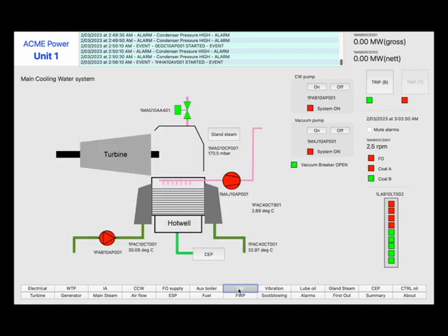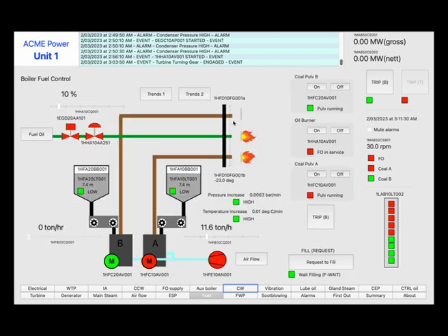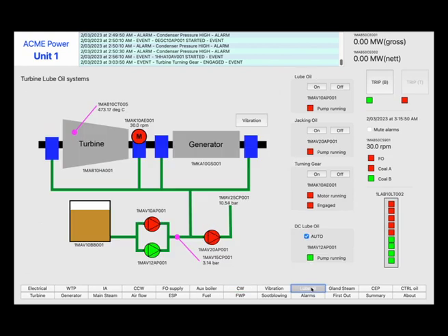Condenser pressure should reduce. Condenser cooling water outlet temperature should also reduce. As our intention is to resynchronize the generator to the grid as soon as possible, adjust furnace burner tilt angle to ensure superheater outlet temperature meets the requirements of a hot start-up. Check turbine oil systems are functioning correctly, and that turbine turning gear has engaged.